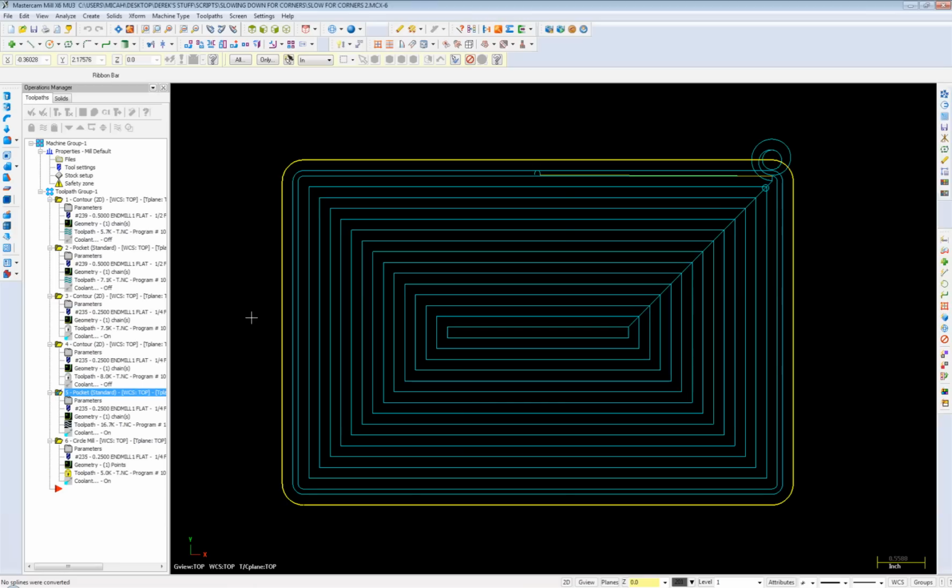Right, and it's good to use screen statistics to do a spline count. Correct. With some software, Pro E can do this a lot, where you bring in a file and it makes everything a spline. So when you try to drill a hole, Mastercam doesn't recognize it as a circle. Instead of picking up the center, it drills at the edge, what it thinks is an endpoint of a spline. So Edit, Simplify would solve that issue. Micah, if you want to quickly click Edit and then Simplify.